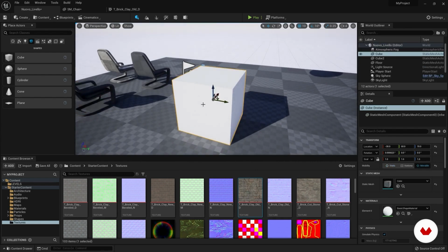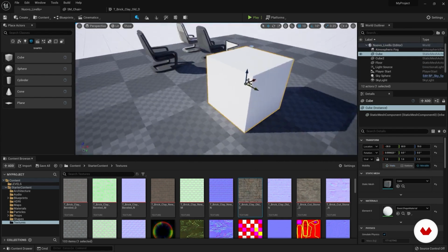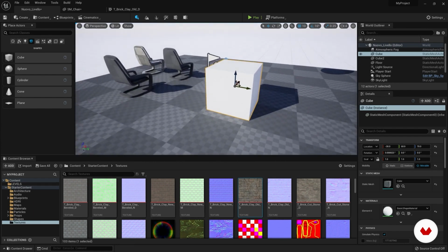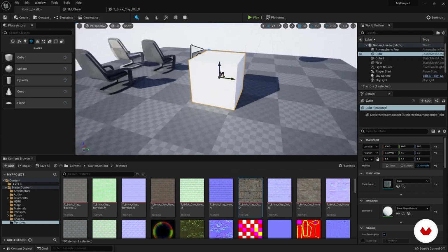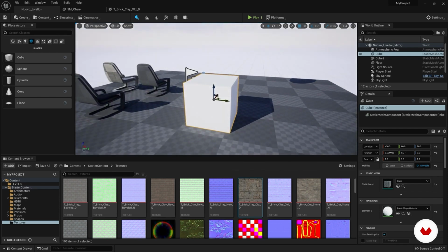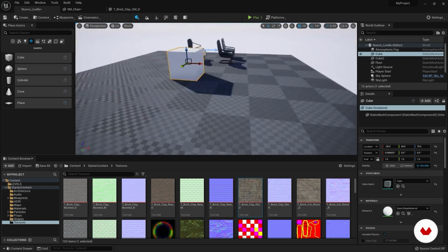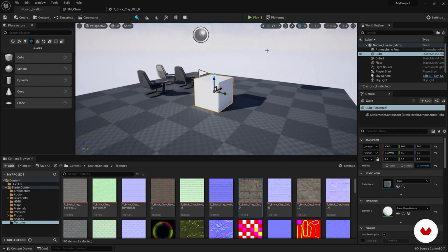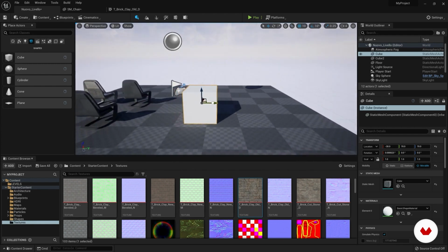An important thing, which perhaps does not really concern the internal logic or the interface, is the snap system. The snap system is essential when assembling a scene. Here we introduce it and make a very brief overview about this function. Snaps are managed here, top right. They can be enabled on surface snapping, or they are disabled. The first snapping we see and which is set by default is this.